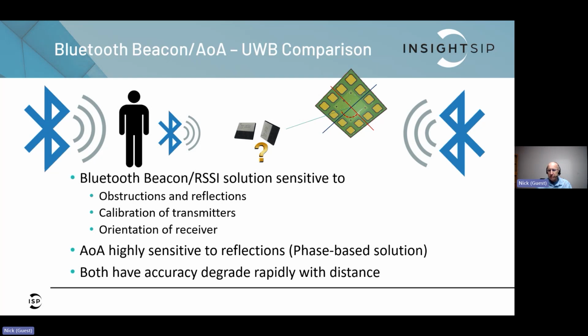So then Bluetooth angle of arrival arrived with a bit of fanfare some years ago. Honestly, it hasn't super well taken off, I would say, and it's very, very sensitive to reflection. So in some environments, it'll work reasonably well, but certainly if you put it anywhere where there's metal around, and that can include anything, including a suspended floor, which often has metal underneath it, you will suddenly start to see all sorts of issues with that sort of technology.